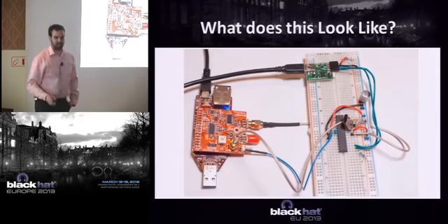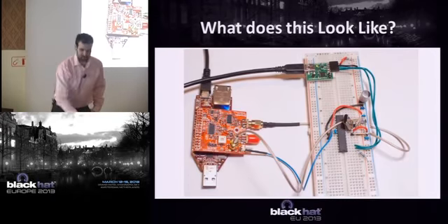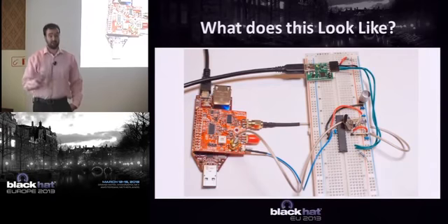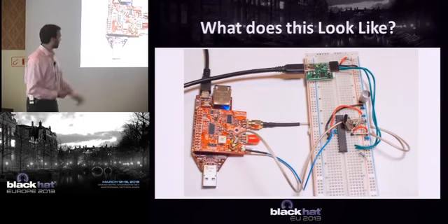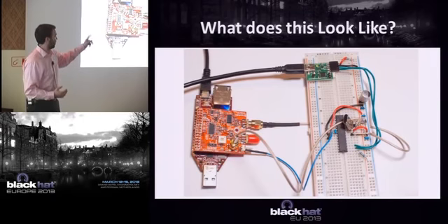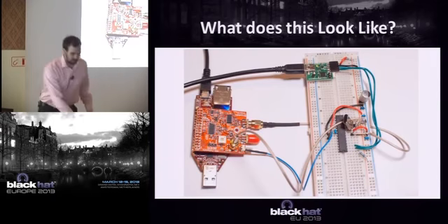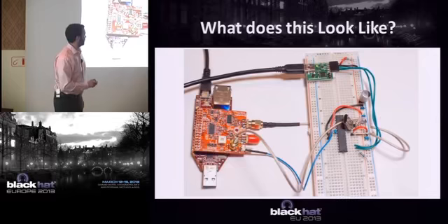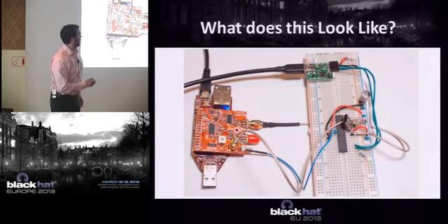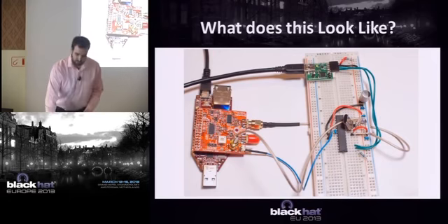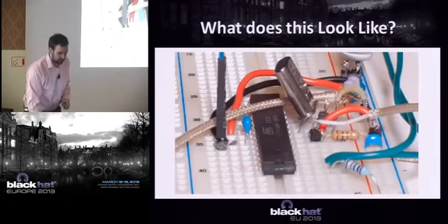So my suggestion, if you are interested in doing this, is to not buy one of those smart cards, because they can be a little trickier to find and expensive, and you need that reader. Instead, just attack an AVR microcontroller like the type used in the Arduino. You can build up something on a breadboard like I have here. We have a crystal, we have a shunt resistor under there, and I'm measuring the power across the shunt. I have the clock frequency coming out here, and I have a little USB to UART board to send and receive data, and also for power in this case.